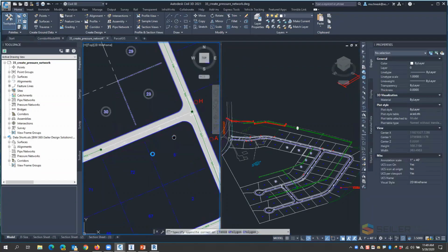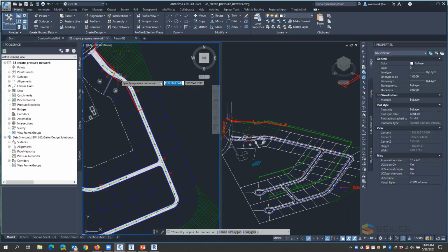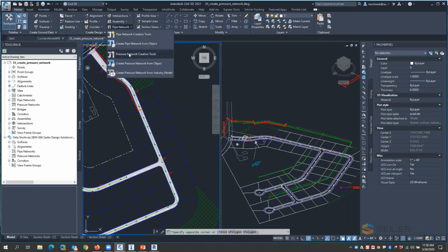So what I'm going to do here is show you the old way we used to do this, if you've looked at previous versions. I could run a pipe between points, and then it would pull from a list of fittings, of the different angles, and it would put the best fitting in there. It only let you go from, if I had 11 and a quarter, 22 and a half, 45-degree fittings, I could only go in those directions. And even though there's deflection allowed in the fittings, it wouldn't take those into consideration when I was running my network.